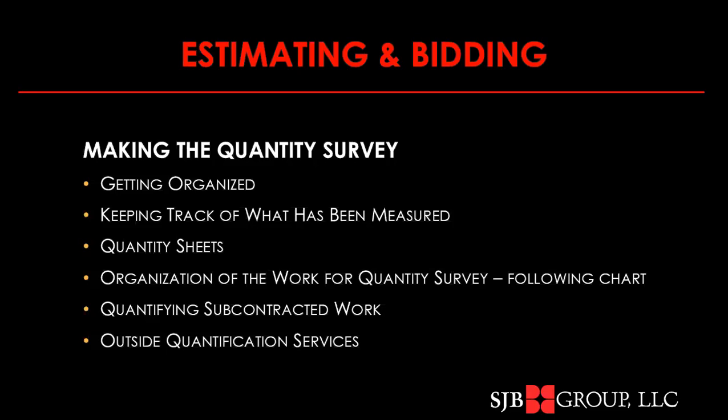You need to break out their quote into the various bid items that it may apply to. And in your estimate, you'll want to have your unit price structure start with the breakdown provided in the contract documents.